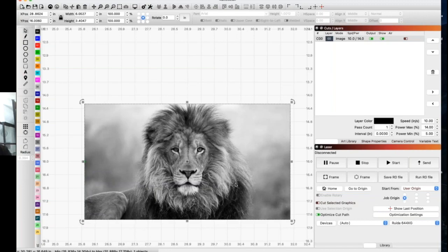It does, because halftone, I tend to find, lays such a tight pattern of dots that it'll blow out a lot of things. It works really well on some stuff. Painted tiles, painted tumblers that have a thin layer of paint, not necessarily a thick Yeti style. Edge lit acrylic would probably be good for edge lit. Surface engraving, yeah, it works really well.